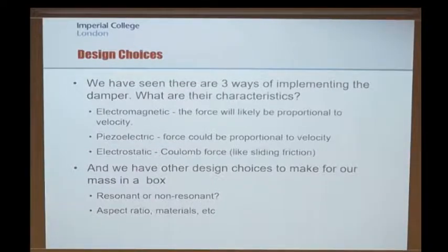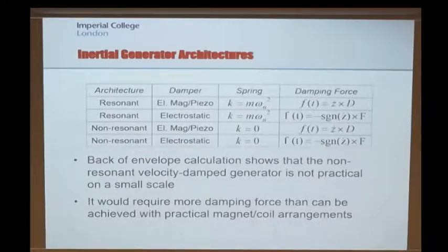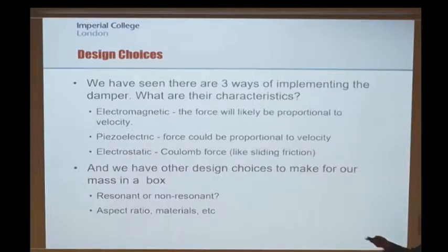Let's take a step back from it and think about whether we really should be tuning to resonance or whether we shouldn't. And then, of course, on top of that, we've got to think about the aspect ratio and the materials and a whole bunch of stuff that goes into the optimization. So, potentially, if we just break ourselves here into saying that we can either make the device resonant or non-resonant as one option, and then we've got electromagnetic or piezo, which are giving us, broadly speaking here,